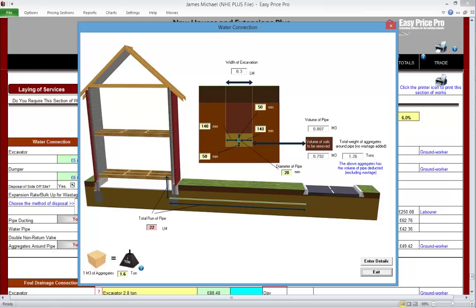The actual depth of the rest of the trench and volume of soils to be backfilled isn't shown. We will be using our judgment for this when entering the excavator, and because the soils that are not being replaced by aggregates will be backfilled, we don't need to allow for their disposal off-site. Therefore, the volume of them doesn't need to be calculated.